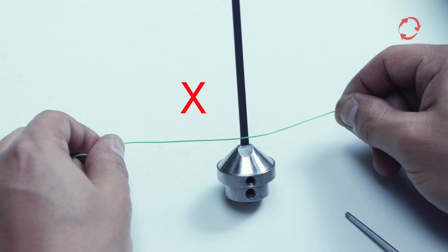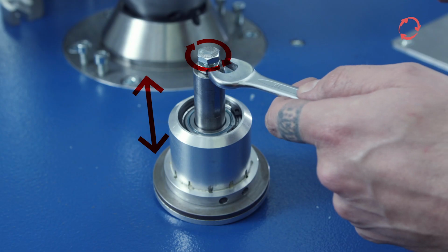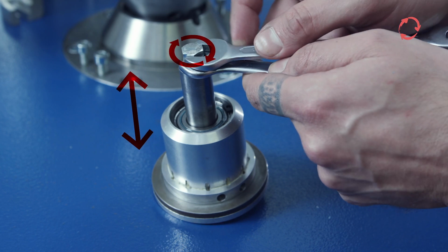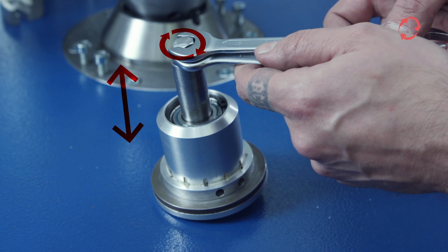If the winding head is too high, the spiral wire will rub against the magnets during the winding process and tear. If it is too low, the winding point on the mandrel will be incorrect, and the desired dimension of the spiral cannot be reached. If it becomes necessary to correct the height, the intake must again be removed from the winding head, and the height must be readjusted on the adjusting screw.